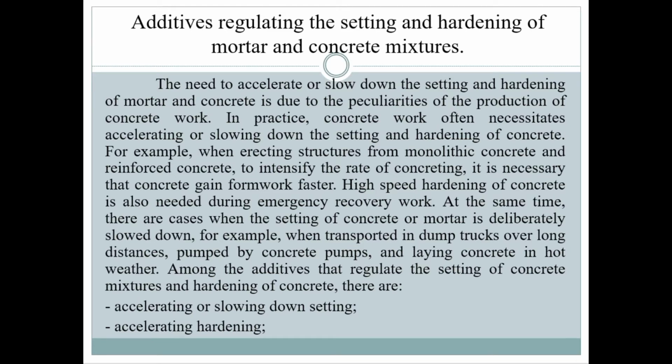At the same time, there are cases when the setting of concrete or mortar is deliberately slowed down, for example, when transported in damp condition over long distances, pumped by concrete pump, and laying concrete in hot weather. Among the additives that regulate the setting of concrete mixtures and hardening of concrete are accelerating or slowing down setting, and accelerating hardening.